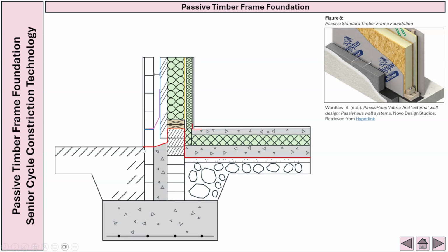Once all that's done, we'll notice now that we put in our damp-proof membrane, our DPM, or our radon barrier, which we know prevents radon gases from penetrating up into the dwelling. You'll notice here that we have our airtightness seal, along with our anchor strap attached to the wall, and we also have our damp-proof course, or our DPC, which prevents capillary action. We also up here have our wall tie.